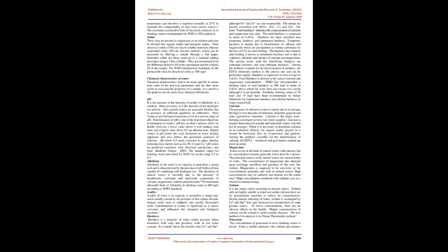Acidity. Acidity of water is its capacity to neutralize a strong base and is usually caused by the presence of free carbon dioxide, mineral acids such as sulfuric, and weakly dissociated acids. Determination of acidity is significant as it causes corrosion and influences the chemical and biological reactions.